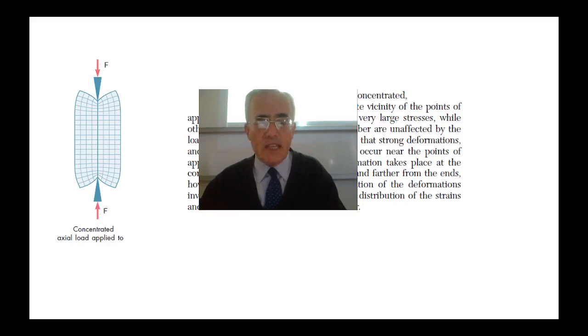Plastic deformation, certainly, yes. The stress in the vicinity of the point of application may be much greater than the fracture limit. So if, when you run the software, the result is greater than the ultimate tensile stress limit, this means you cannot use this object in that size, with that material, and under the action of such a loading.